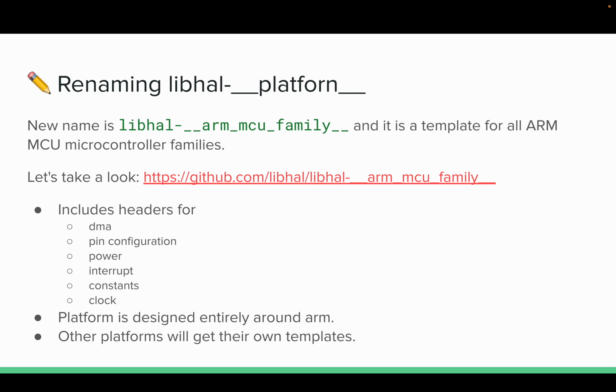Here are some links to some linker scripts. This kind of defines how linker scripts are kind of set up, because if you notice, for these, we have STM. Let me zoom in a little bit. We have STM32F10XX4. That last digit here, that last character, is basically an indication of how much ROM is available, because the RAM is actually fixed.